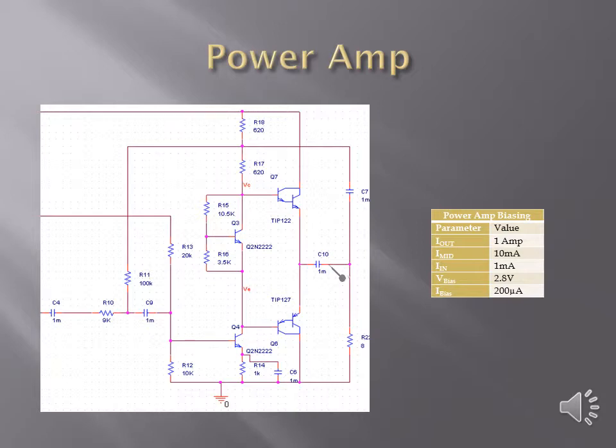A voltage of approximately 2.8 volts is required at the VBE multiplier to compensate for the turn-on voltage for both Darlington paired transistors. A base current of 2 microamps was selected for the VBE multiplier, which is more than enough to avoid the risk of a cutoff condition.